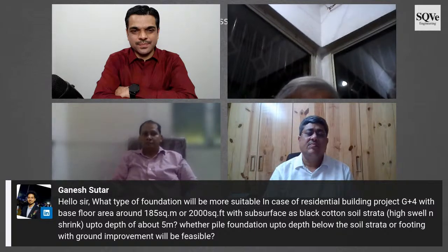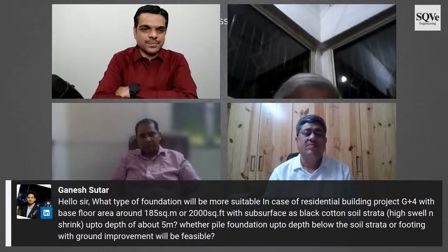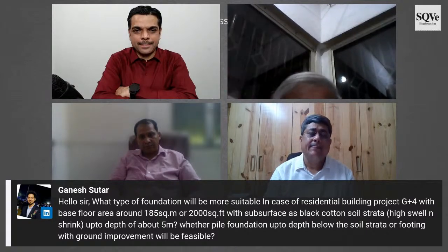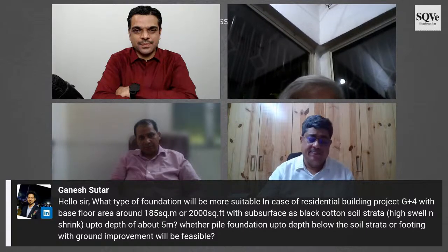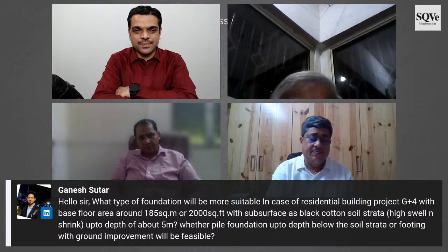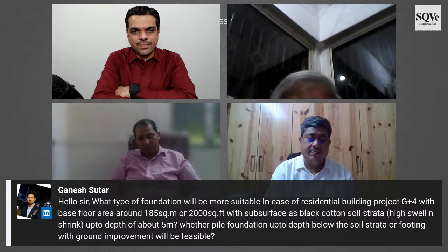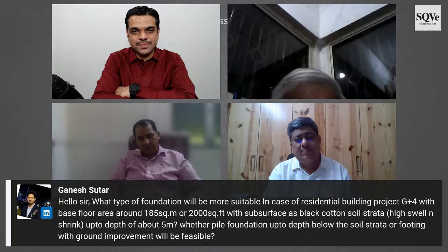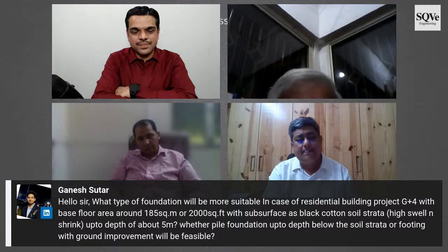Second, you allow the swelling pressure to come in, like Sandeep talked about plinth filling. What we did was we created a hollowness in the brick, like rat trap bond bricks, which Laurie Baker was using. So we filled up the hollows so that the soil is allowed to swell. You don't restrict it. The moment you restrict something, the question of force comes in. If you allow the movement, the force does not come in, because it's not the settlement that we are talking about. It is the uplift because of the swelling pressure that we are talking about.